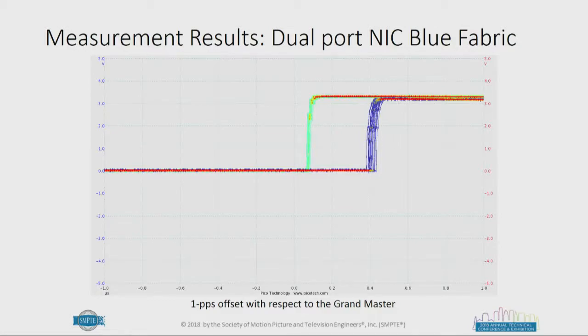This is normal because this is how PTP operates. Remember, every single time you actually have an operation with those 4 messages and the fact that you have 8 messages per second, you are basically drawing a new result, and therefore there's always a slight variation. This should not worry you in any way. This is absolutely normal in terms of how PTP and how a 1 PPS signal is generated out of the PTP. What's going to be interesting is what you see now on the next slide, which is when I actually do the exact same graph, but on the red fabric.